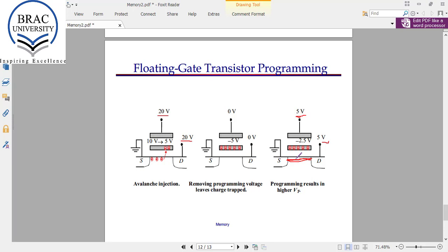So in this way we can disable some transistors from our chip, and this is how we can program it. And now what about erasing? How can we erase this? We cannot erase this electrically because there is no way we can remove these electrons from this metal layer to this semiconductor electrically, but there are some other ways.